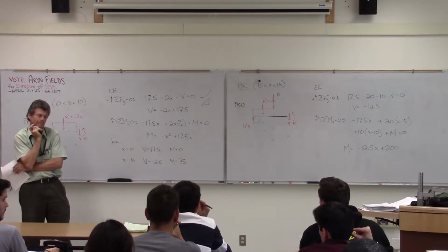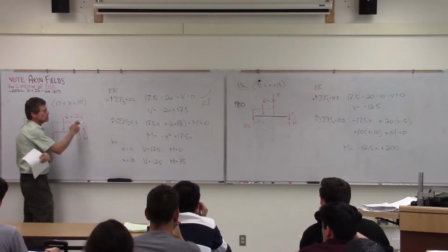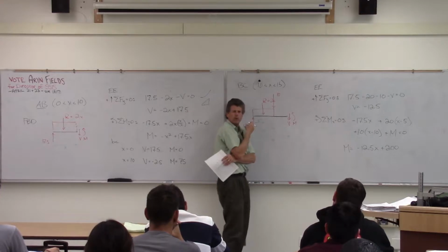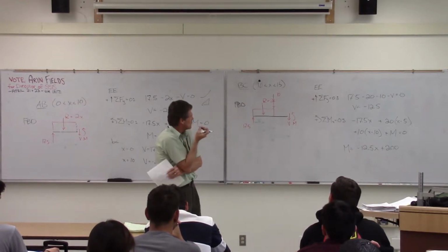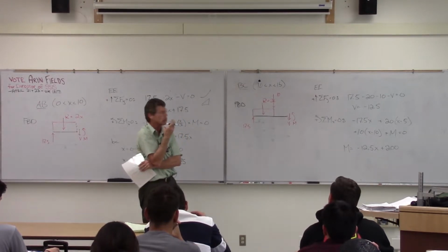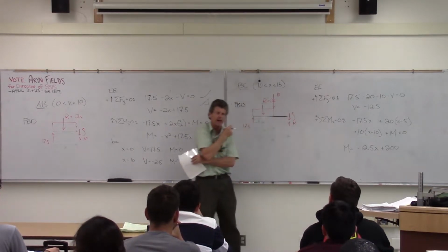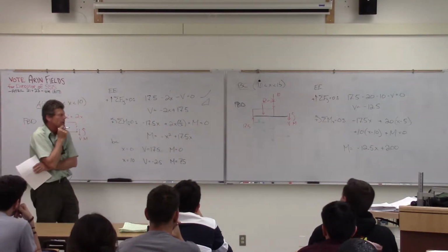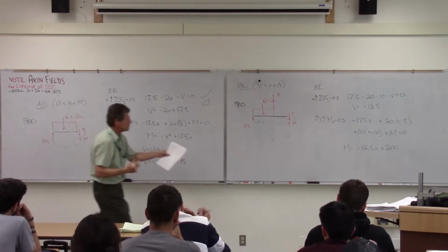Yeah, that's what we're kind of doing when you think about it here, is that 10 kip load we don't know. It's a concentrated load, the vector, we would have to go into higher mathematics. What we do is we just simply trick it by cutting on this side and then cutting on that side. And what we'll see in the diagram, I'll explain to you why it looks like it does. But we'll see a jump basically in our diagram. But let's finish up here then.